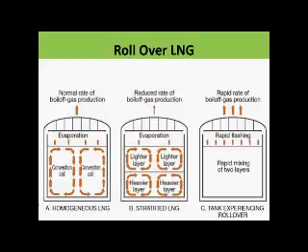It falls down. It falls down because the evaporation slows down from the top, because all the methane molecules have gone. And now there is a heavier molecule which needs more heating. For example, propane boiling point is around in the region of -50. Butane is around nearly zero, just above that. They do not want to evaporate, so they become heavier. And suddenly, what happens in a rollover position? They just roll over at the bottom.